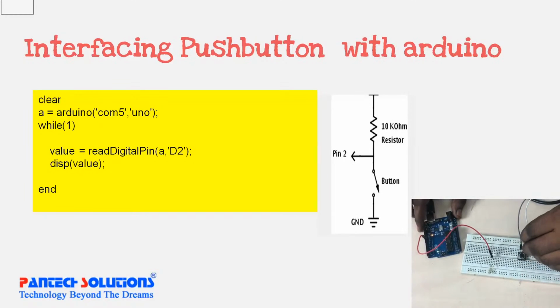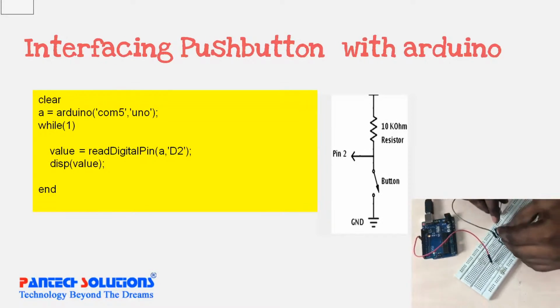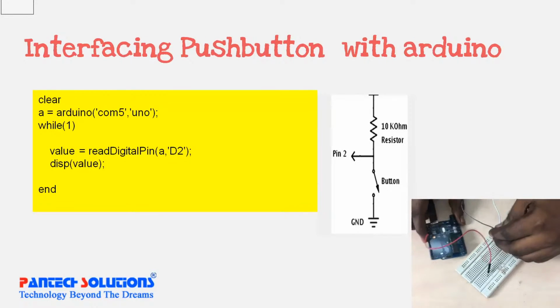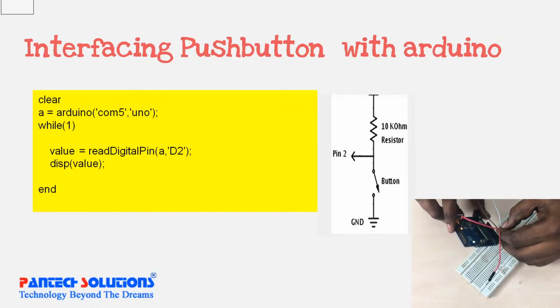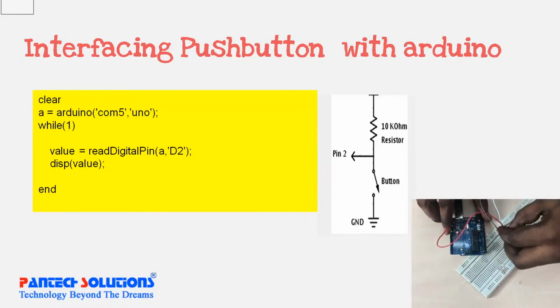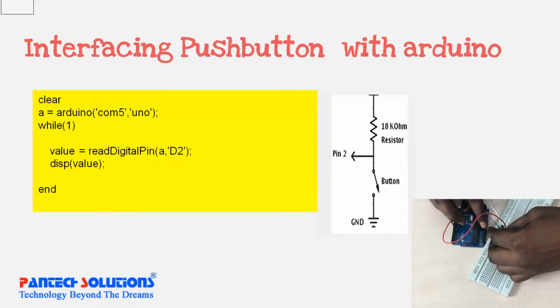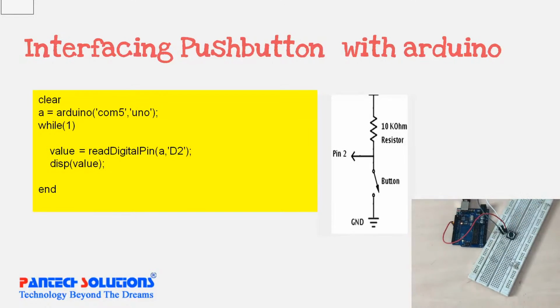This push button, I'm going to connect a 10K resistor to VCC. This to D10. Okay. So this is the connection.